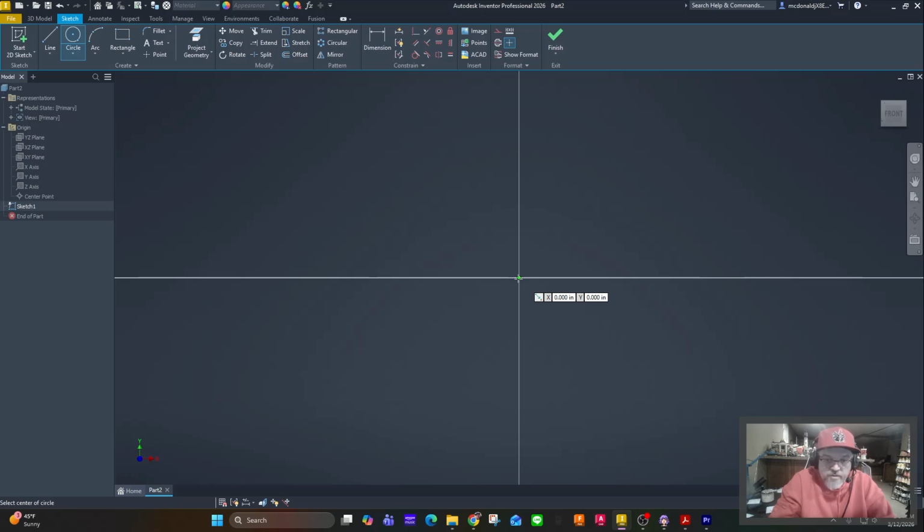Think 3D printers, CNC mills, routers, things like that. A lot of furniture companies mass produce with repeatable holes and sizes. That's how you make something fully reliable every time. So if you use the origin in your sketch, it helps fully constrain and define your part a lot easier.